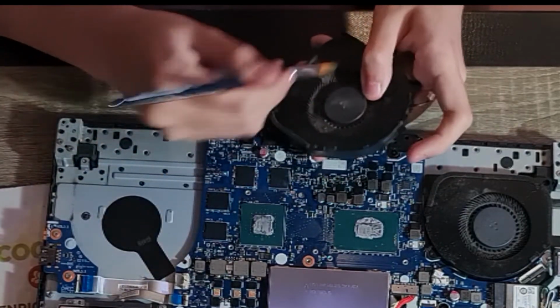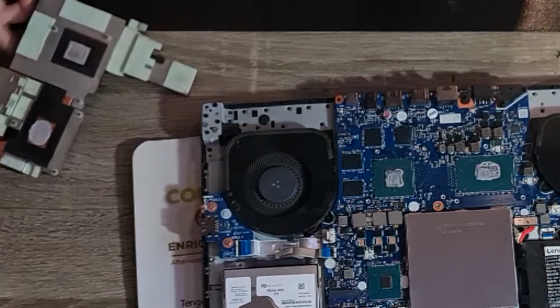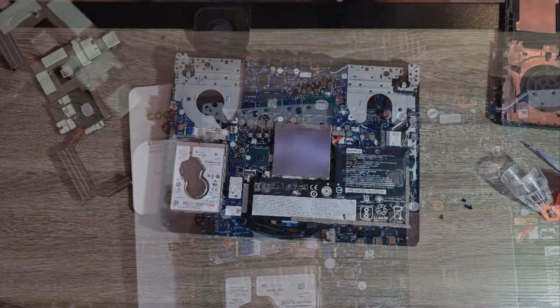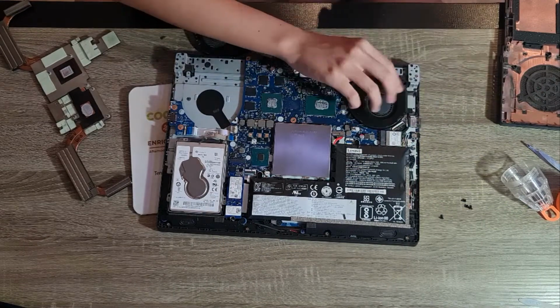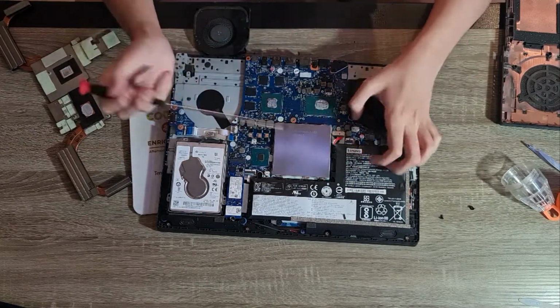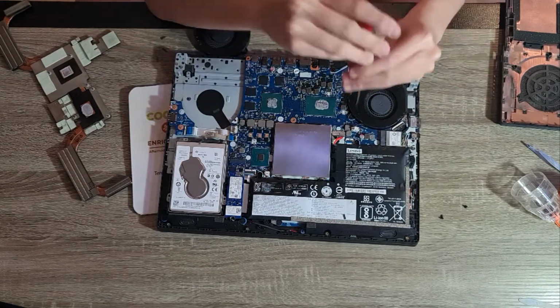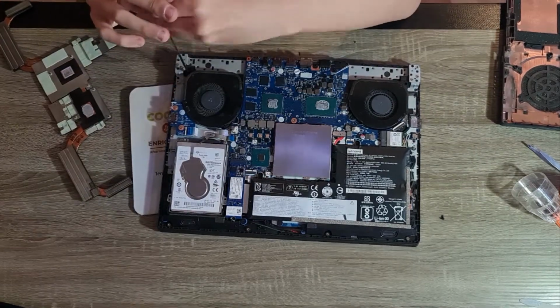Sixth, clean the fan using a small soft brush, and also clean the heatsink with a brush if any dust has accumulated. If your fan is broken, as the fan doesn't have any dust with it not producing any airflow, replace it with a spare original fan from the laptop's manufacturer. Seventh, place the fan back to its original position. Screw it tightly and reattach the cable to the motherboard.